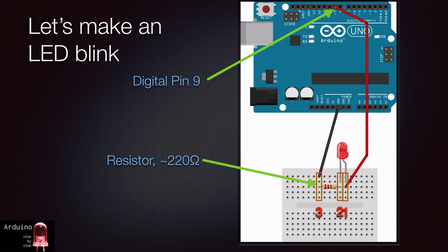Connecting our resistor in series with an LED is important because the LED does not offer much resistance to electricity. Connecting an LED directly to power will cause a high current to flow through it and quickly burn it. Now here is a tricky part that has to do with connecting the LED in accordance with its polarity. Take the LED, find its long leg, and plug it into an empty socket in column 1. This socket conveys the positive voltage.